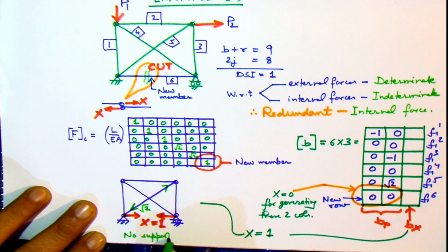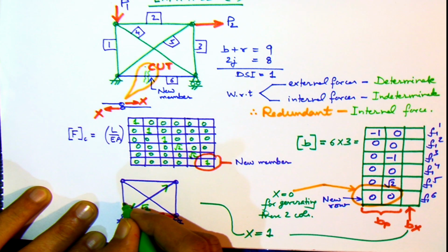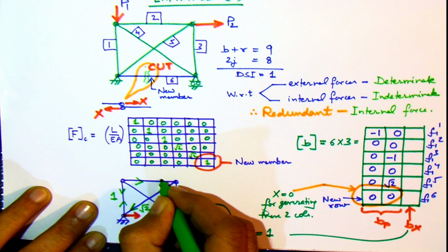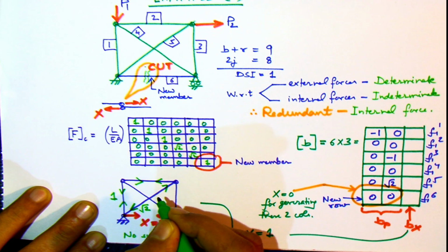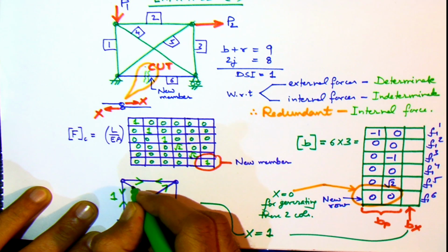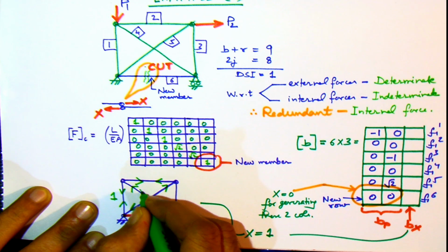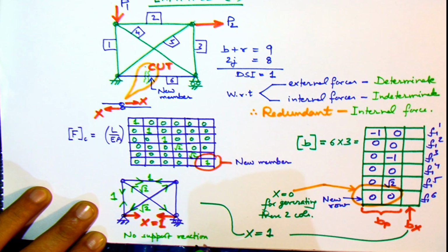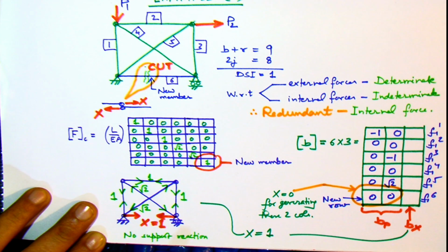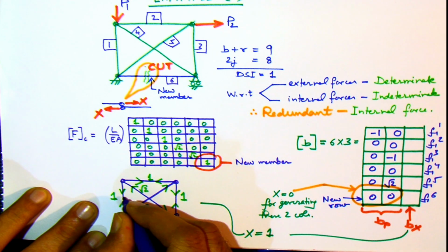So we begin with the left support. Here the force in the diagonal bracing member is a compressive force equal to root 2 newtons, and then once we have this, going by the equilibrium, we can find out forces in all other members. So what we find, the two diagonal braces have compressive force equal to root 2, and all the other members, the vertical members and the top horizontal member, have a tensile force equal to 1 newton.